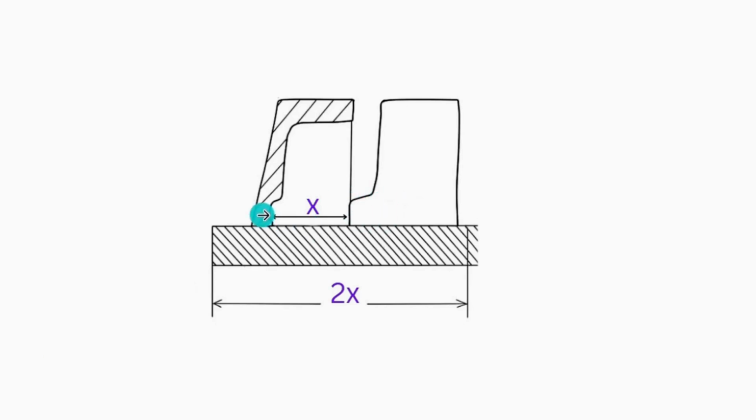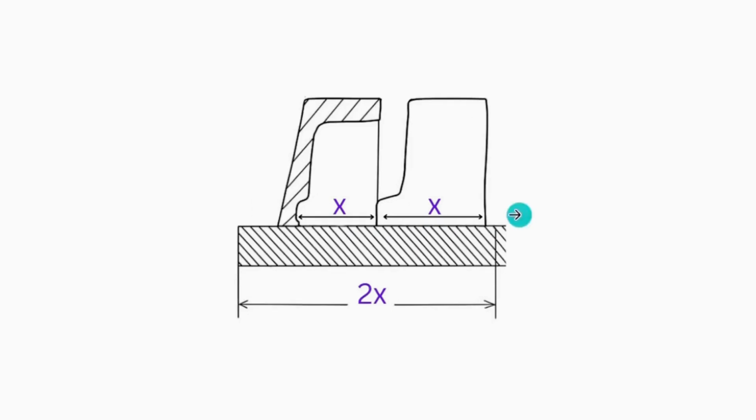And this is the slider. When your slider moves x distance, the actual travel from here to here is 2x, because this is also x. You can see this now. The slider block is also x, and the undercut is also x, so travel is 2x, right? Yes. So when you are traveling 2x, this edge is going to hit when it comes up, right? Yes.